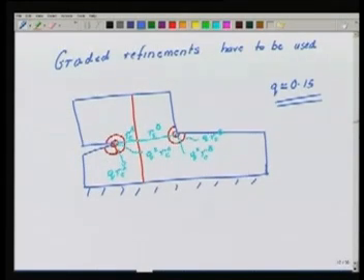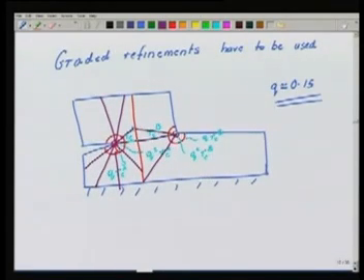So now you make the mesh. One way I can make the mesh is, let's make elements going like this, and so on. I am not trying to complete the whole job. So I will make these rings in this way, and then I can complete the mesh. So what do I do? I do this graded refinement towards the singular corners.